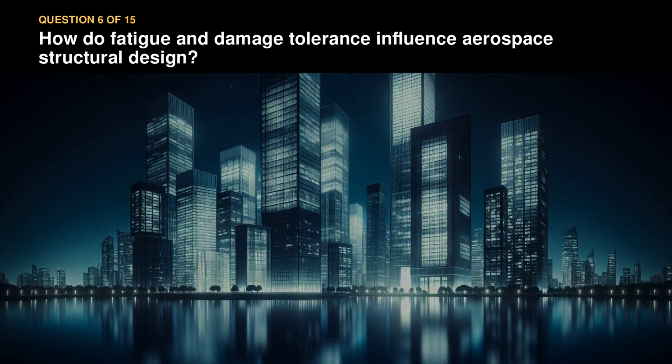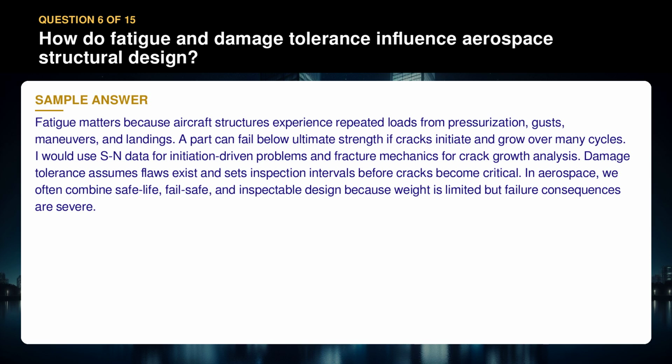Question 6. How do fatigue and damage tolerance influence aerospace structural design? Fatigue matters because aircraft structures experience repeated loads from pressurization, gusts, maneuvers, and landings. A part can fail below ultimate strength if cracks initiate and grow over many cycles.